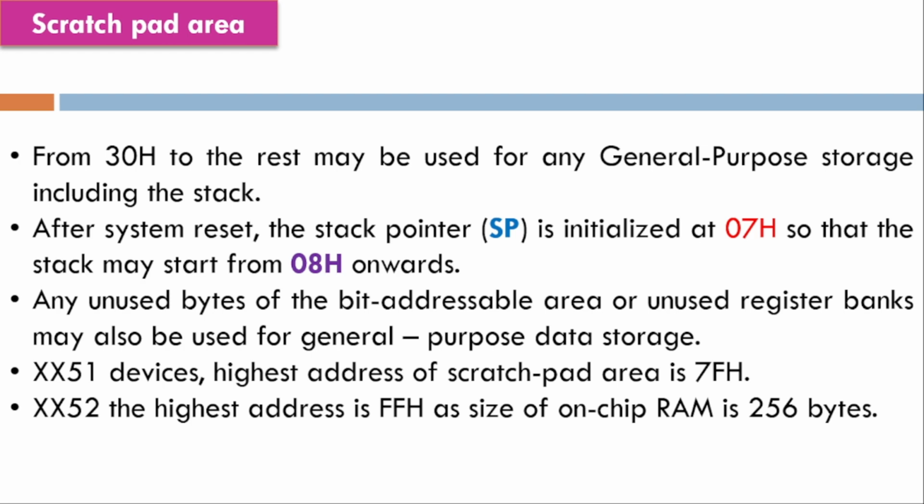storage. In MCS 51 devices, the highest address of the scratchpad area is 7F hex. In MCS 52, the highest address is FF hex, as the size of on-chip RAM is 256 bytes.